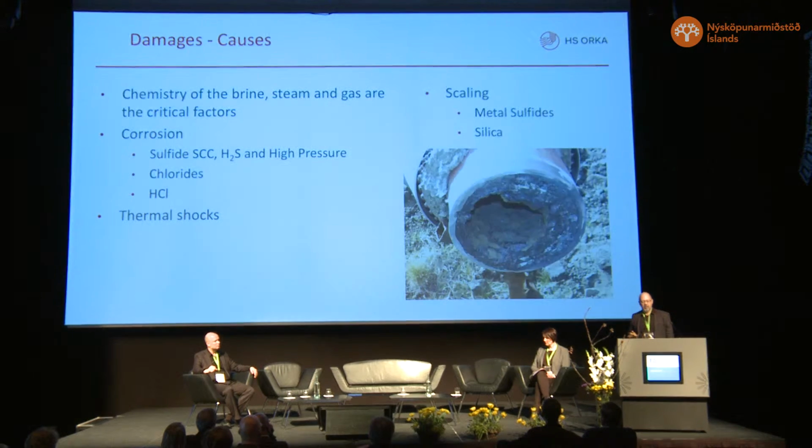Silencer for flushing brine. Of course, and as I said, the roots are in chemistry, start and end in chemistry. We have various kinds of corrosion. We must be careful of thermal shocks, and we have a lot of scaling. This picture showing metal sulfide scaling in a pipe from well 11 on Reykjanes.